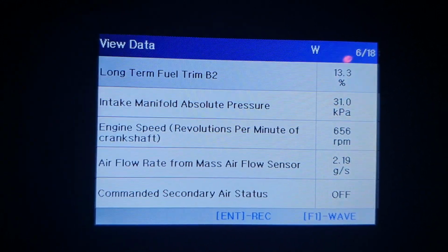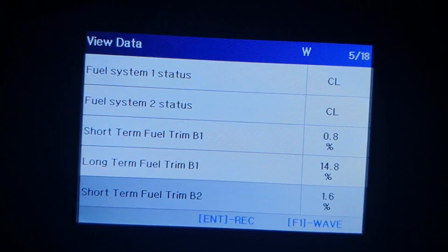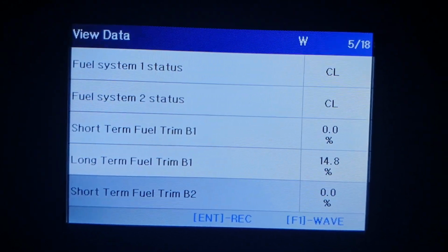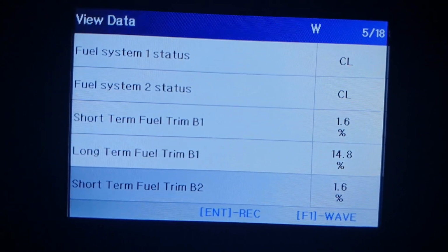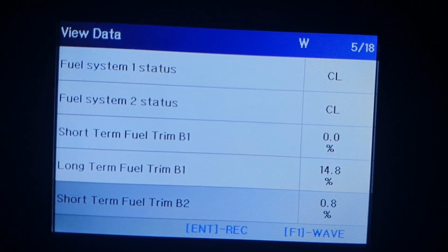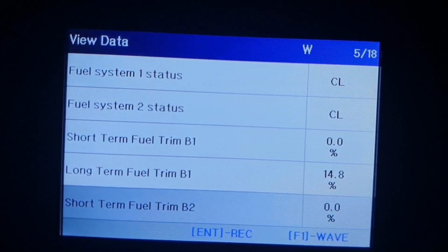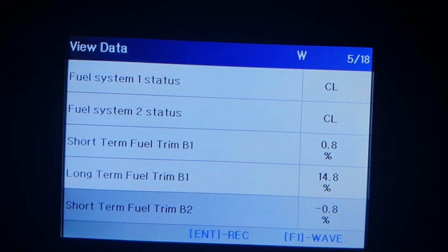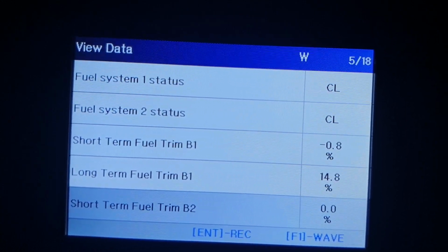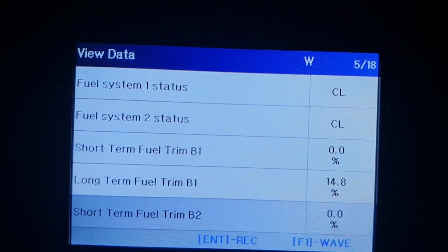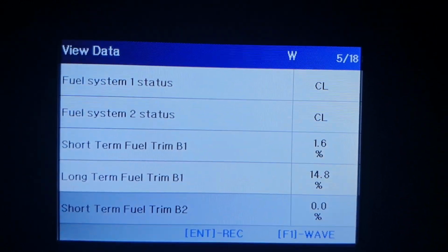But anyway, it seems to me like the mass airflow sensor is working, because otherwise it wouldn't have detected increased air intake when I rev the engine. So looks like I've drawn the right conclusion about the mass airflow sensor working. Now the question is, where is the air intake leak? It's obviously somewhere after the mass airflow sensor. That's one question that needs to be answered, and I'll try to figure out if there's a way to.